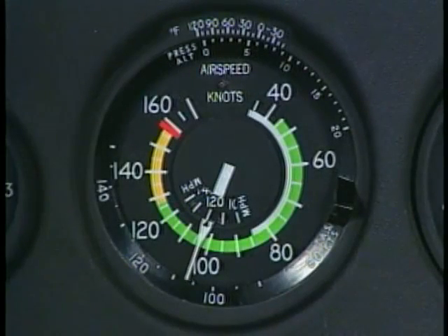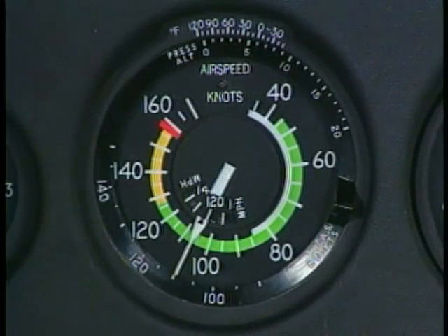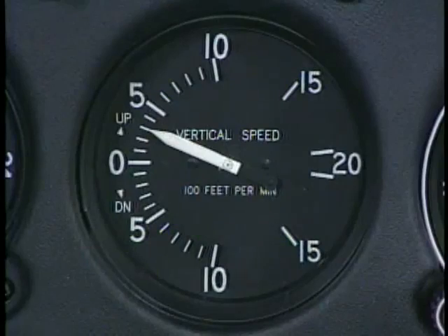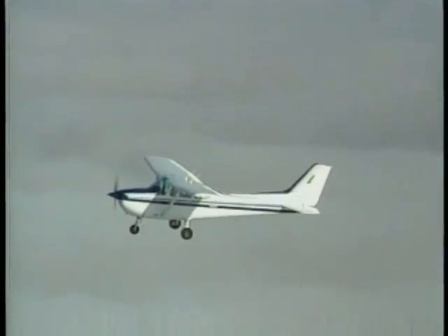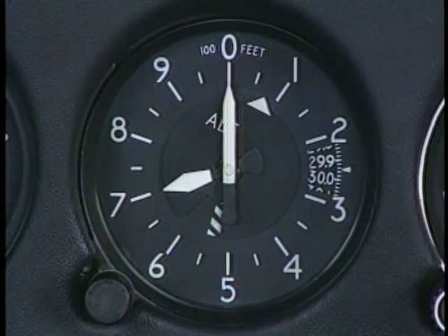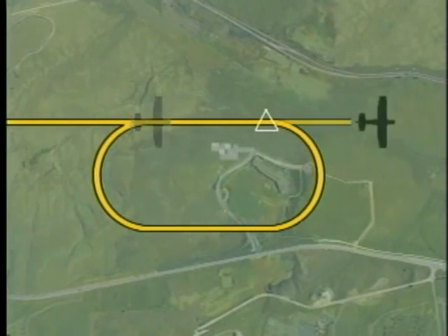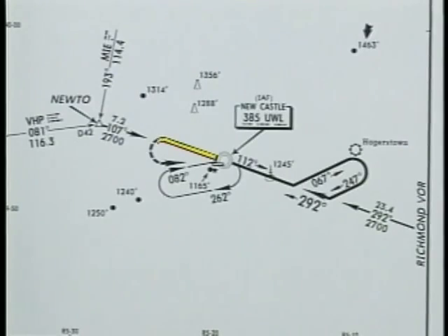Other reports include a change in the average true airspeed of 5% or 10 knots, whichever is greater. You should also notify ATC if you cannot maintain a climb or descent of at least 500 feet per minute. Other reports include the time and altitude when you reach a holding fix or point to which you have been cleared, leaving an assigned holding fix or point, and initiating a missed approach.